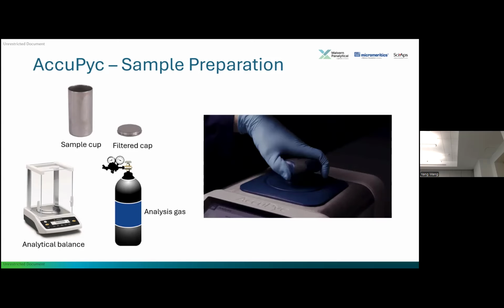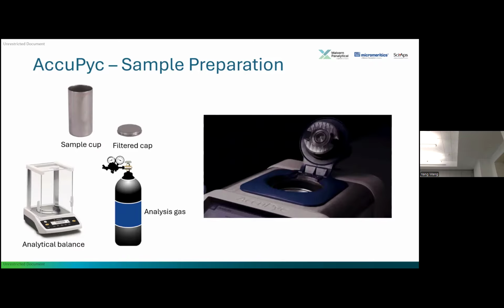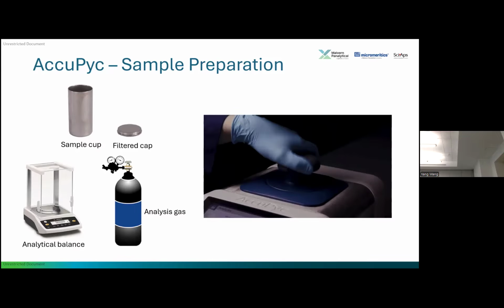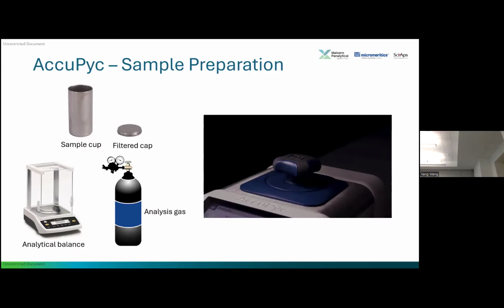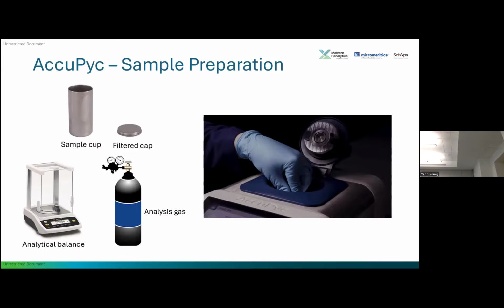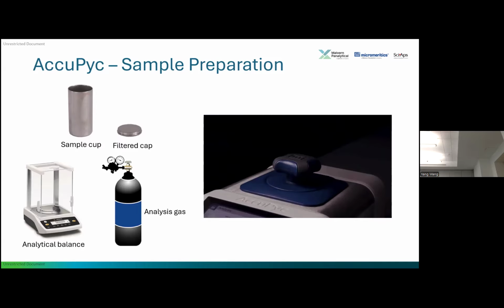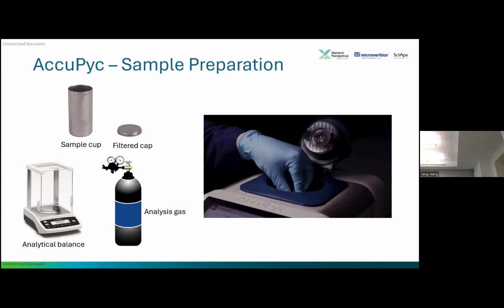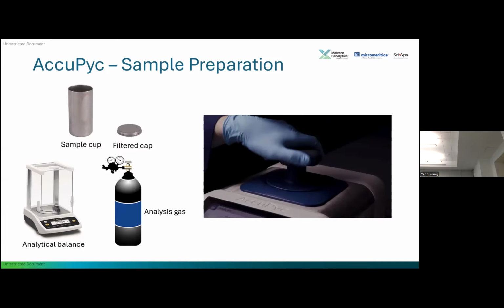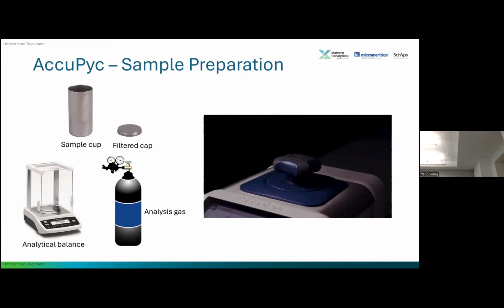As far as blending gases, you can, but it's not really common. Like I said, air is a combination of nitrogen and oxygen, but the main thing is you have to know the properties and compressibility and things like that for the measurement. This system comes with all the calibration. Yes, all that stuff's built in.